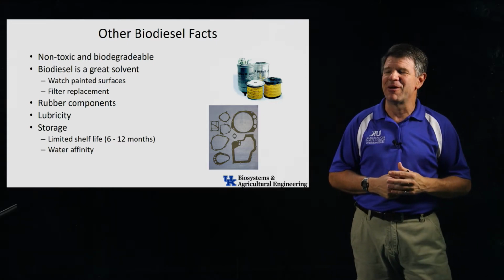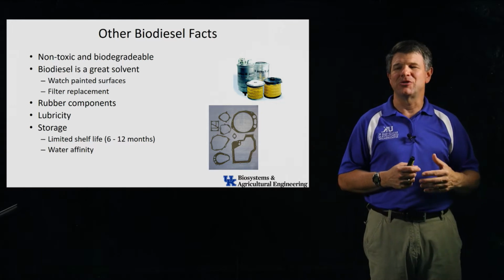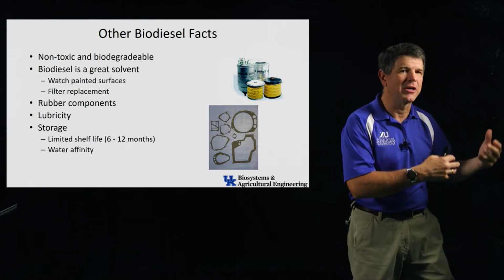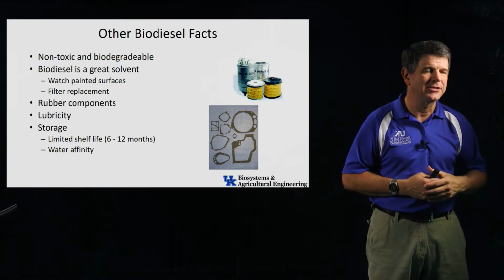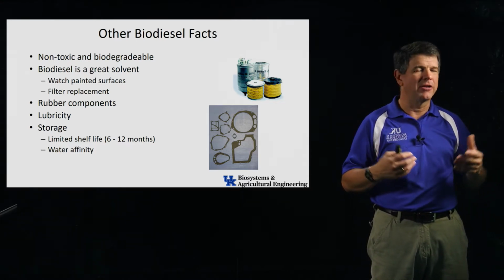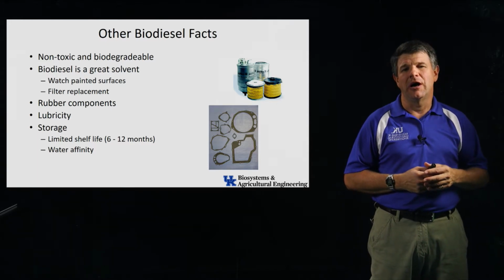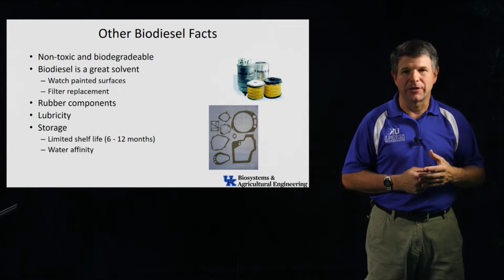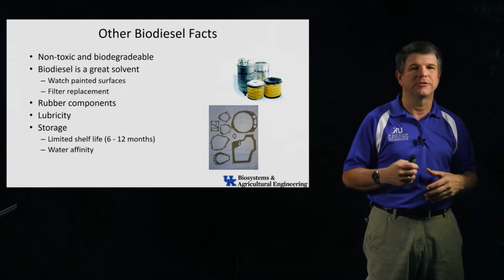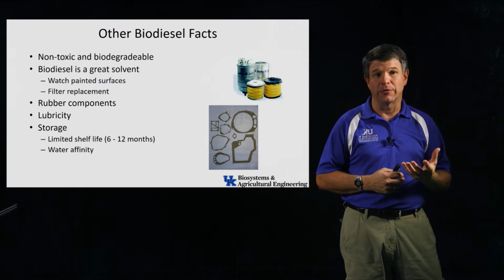But the interesting thing you run into is filters. We had a situation a couple years ago where we had a machine that we developed in our department, and we took it out to a cooperating farmer to test the machine on his farm. It was a multi-day test. We ran it the first day and it worked really great. At the end of the day, we filled up the fuel from the farmer, and the next day we worked for about an hour and the thing shut off. The technicians ran around trying to figure out what was going on with it, and finally figured out the fuel filter was plugged up.